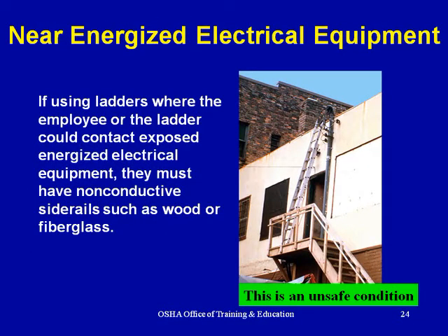Near energized electrical equipment. If using ladders where the employee or the ladder could contact exposed energized electrical equipment, they must have non-conductive side rails such as wood or fiberglass. This is an unsafe condition.